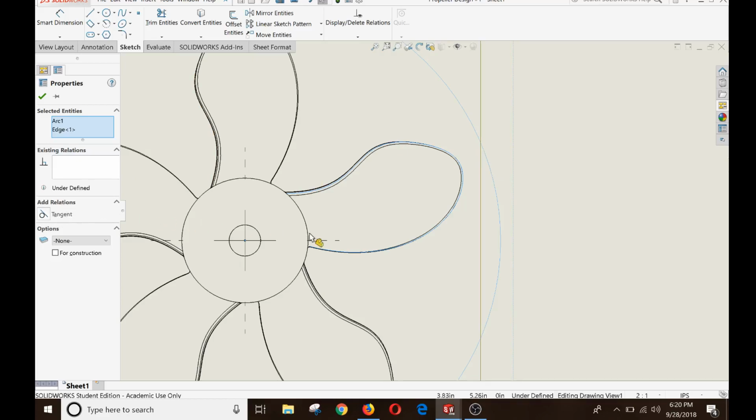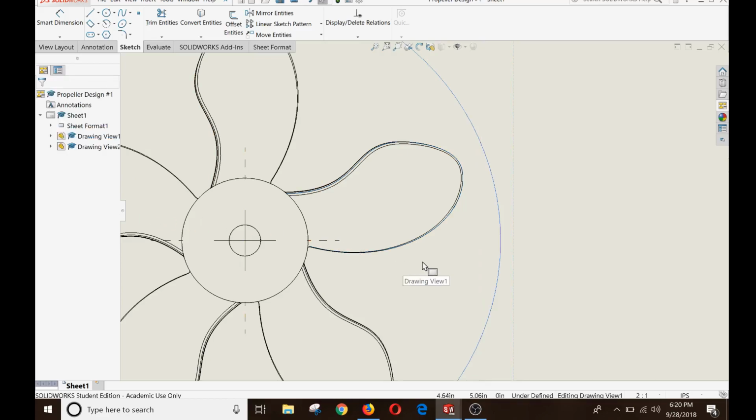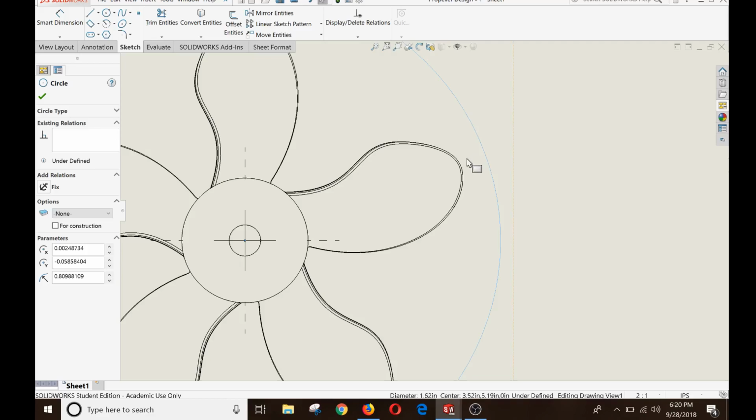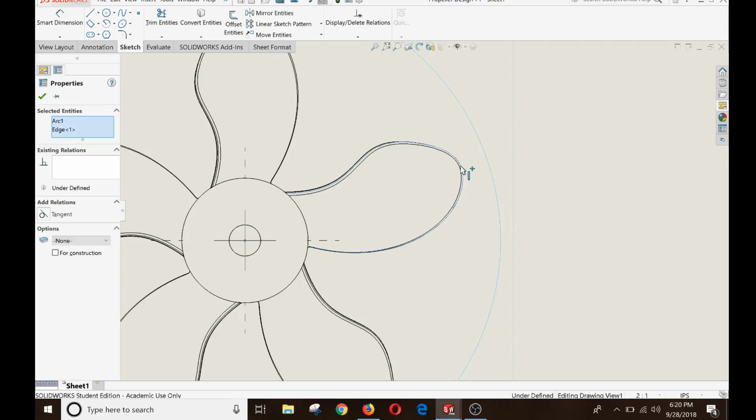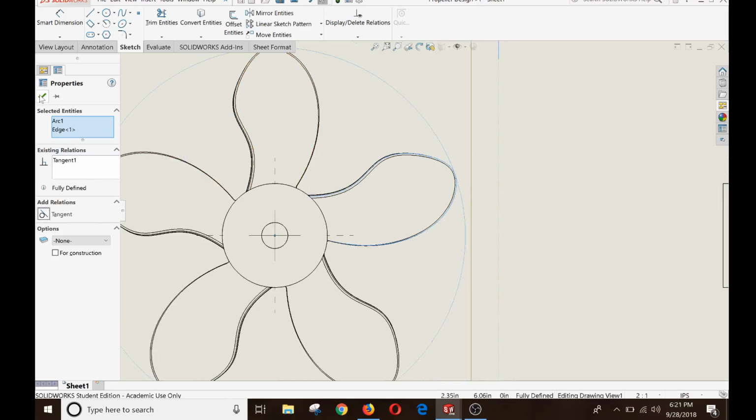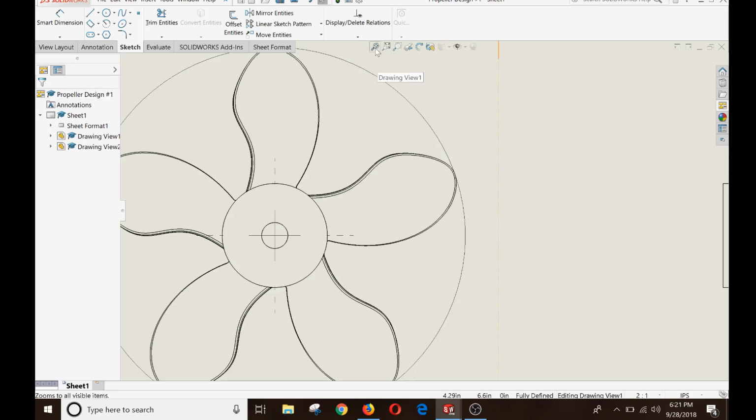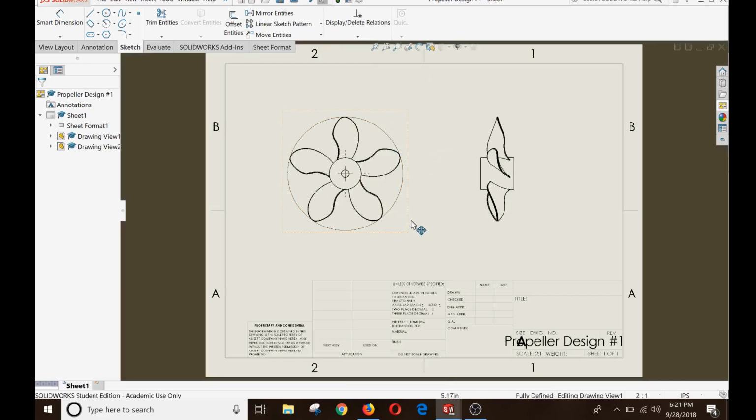This is tangent. Okay? But before I do that, let me just show you again how to do this. So you're gonna be here. You're gonna click once here. Now shift key and go find this one and click there. Now you have them both blue. You're gonna go to this properties manager and click the tangent. Before I click, check what's gonna happen here. Okay, I click tangent, and boom, it goes exactly what I wanted around it. Okay, gonna check mark, and I'm gonna go look at the whole part. Now I have everything I need.